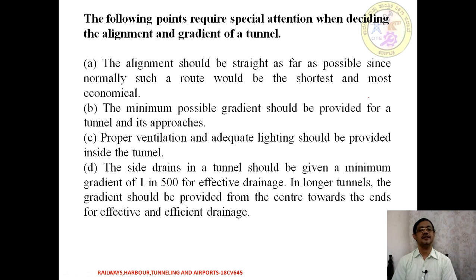The side drains in the tunnel should be given a minimum gradient of 1 in 500 for effective drainage, and in a longer tunnel the gradient should be provided from the center towards either end for effective and efficient drainage.